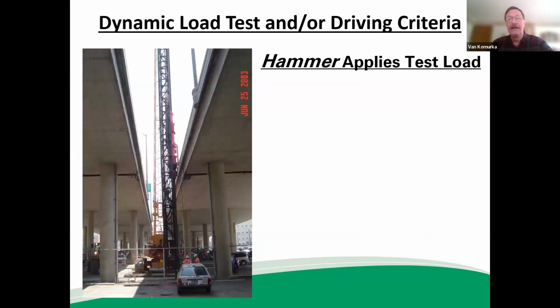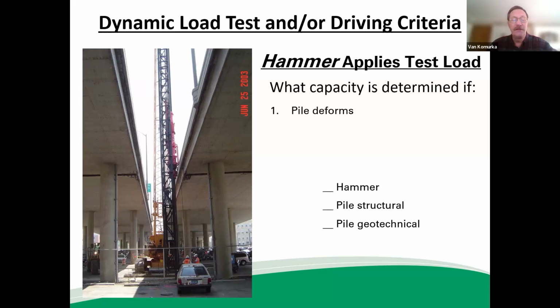So let's then segue and apply that to when you're driving a pile and the hammer applies a test load. All right. So what capacity is determined if the hammer is driving the pile and the pile deforms? Well, you've determined the pile's structural capacity. What if the pile is advancing through the soil? Well, you're failing the pile geotechnically, plunging it. So you're determining a pile's capacity.